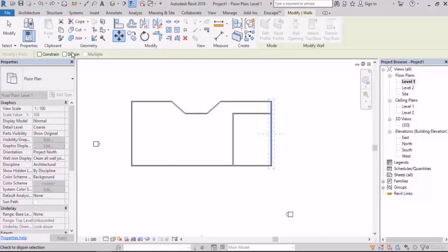And you get angry and say, what is the relation between these two? Why did that one move? As long as you don't activate this disjoin, it might move anything with it. So please remember that anytime you see that something moves without you wanting it to, it's because of the disjoin and you need to activate it.